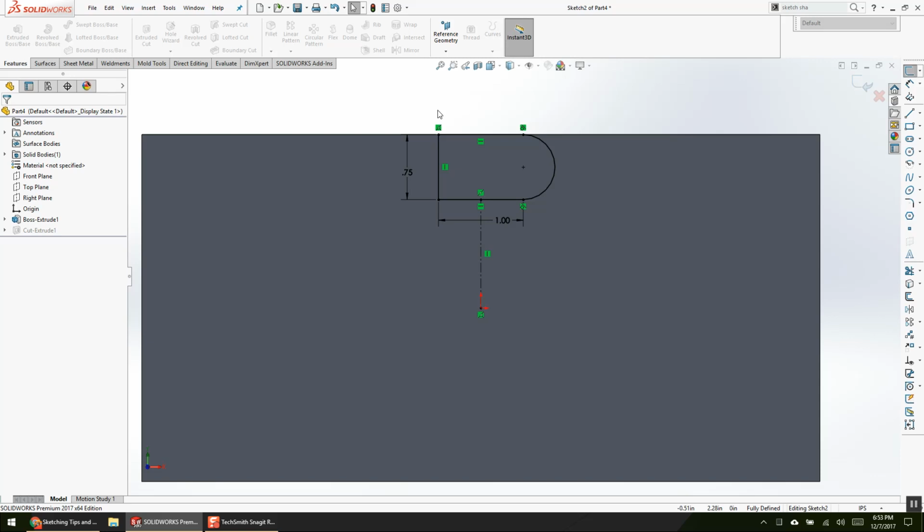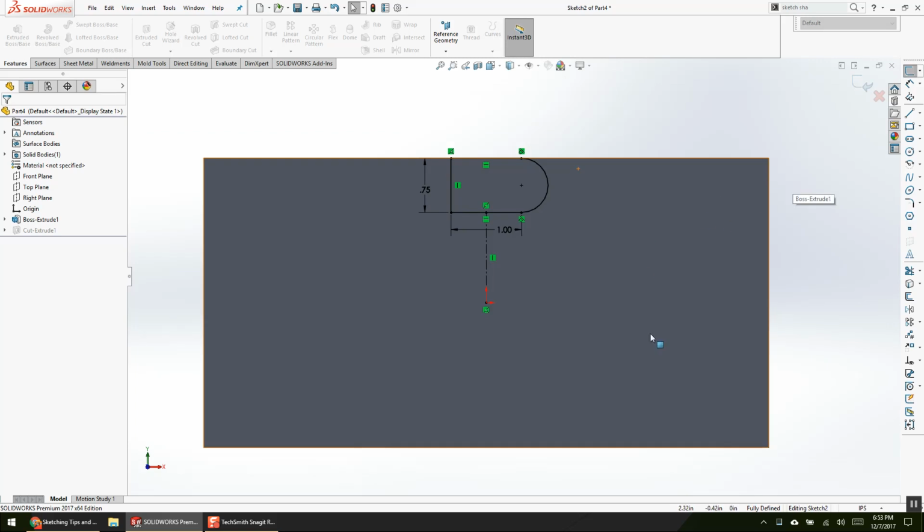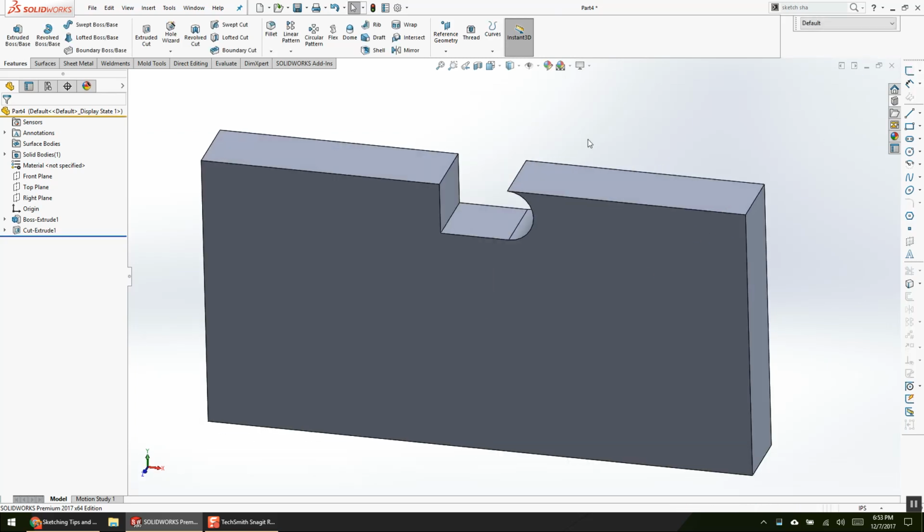I hear you say it's best practice not to import your dimensions from the model, but do them on the drawing instead. Because what dimensions here are helpful for the machinist? That's what you're saying, right? None. Best practice. Yep, so I'm not going to go out of my way to add dimensions in my 3D model that aren't helpful. So you typically wouldn't import any? None.